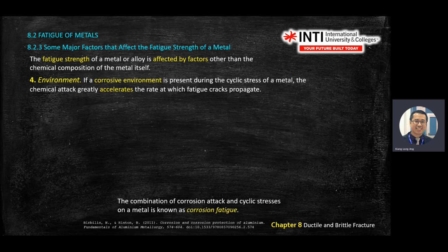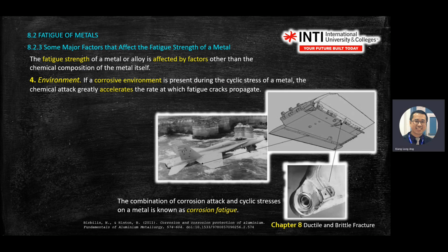Number 4 is environment. The environment of the fatigue. So if you're near to corrosion environment, for example, if you're near the sea, or you're near to those chemical plant, then you will accelerate the crack rate. It's more on the chemical attack.